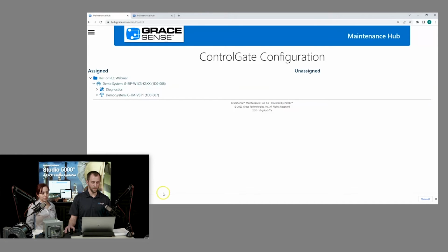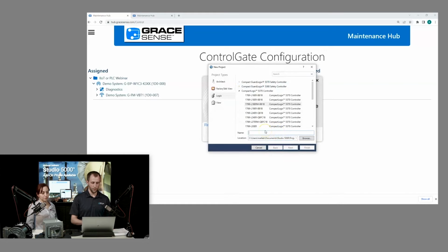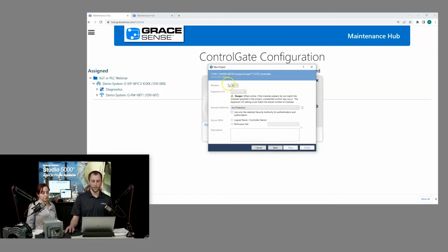You'll see it popped up down here, and I should be able to use that when I start Studio 5000. So let's dive into Studio 5000 and start a new project. We are going to name this IIoT PLC webinar. A key thing here is you'll notice that I am on Studio 5000 version 35. This is the new one that Rockwell released back in November, and it has our AOP pre-installed. If you're using an older version, like many of our customers are, you can reach out and we can distribute that AOP to you, and you can ingest it and bring it into your Studio 5000 environment manually. But if you upgrade to version 35, it will automatically be there.